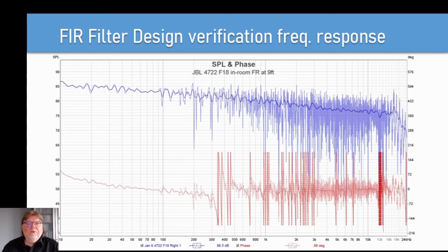If the transfer function was not working as designed, we would see a different frequency response past the diffusion zone, with either too much or too little mid-range or high-frequency energy. Here the response adheres to the design target perfectly with very little frequency response variation. Note that one can apply less correction and get more variance in the response. It is interesting and educational to listen to the same transfer function with varying levels of correction applied. Most folks opt for the smoother sound as it's clearly audible in an A/B test using Hang Loose Convolver.